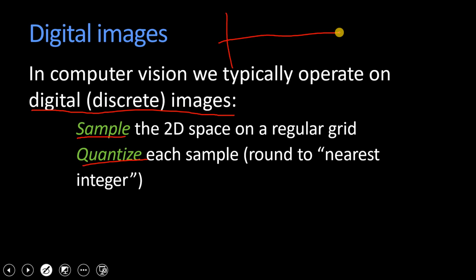So if you remember in your signal processing course, let's say you have a pure sine wave, a signal. So this is your signal S. You want to convert this signal into a digital signal. So this signal is analog. To convert it into digital form, the first step is you will do sampling. Sampling means that you sample or measure the value at fixed intervals.